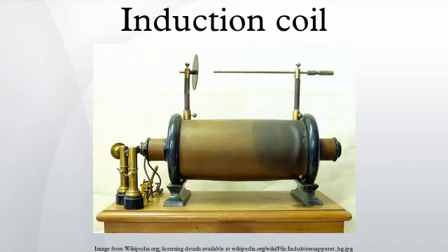Therefore much research went into improving interrupters, and improved designs were used in high-power coils, with the hammer interrupters only used on small coils under 8 inches sparks. Léon Foucault and others developed interrupters consisting of an oscillating needle dipping into and out of a container of mercury. The mercury was covered with a layer of spirits which extinguished the arc quickly, causing faster switching. These were often driven by a separate electromagnet or motor, which allowed the interruption rate and dwell time to be adjusted separately from the primary current.